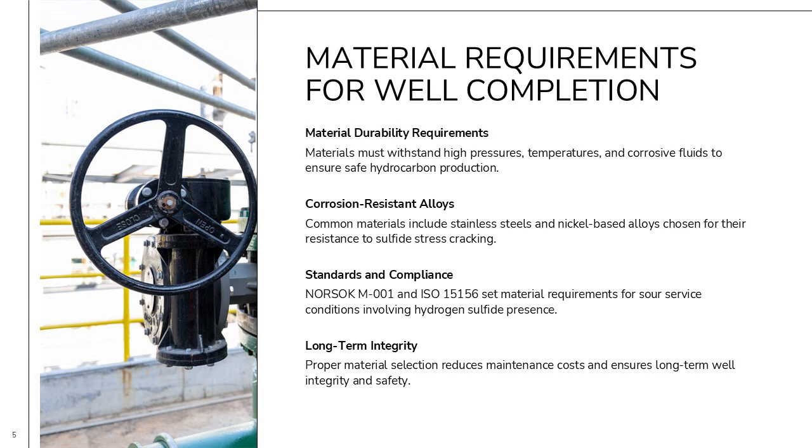NORSOK M-001 emphasizes the need for materials that can handle sour service conditions, where hydrogen sulfide or H2S is present, requiring compliance with ISO 15156 standards. Proper selection ensures long-term integrity and reduces maintenance costs.